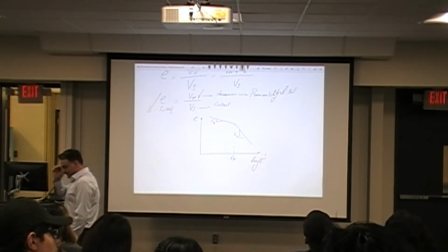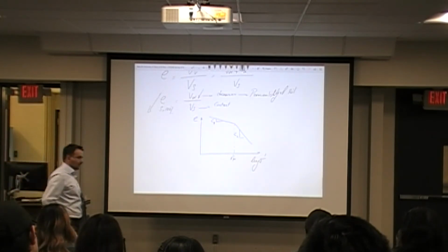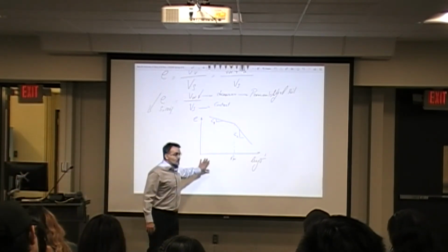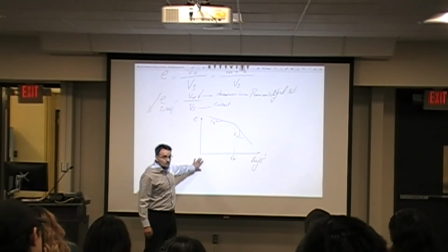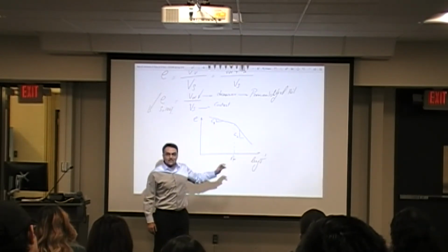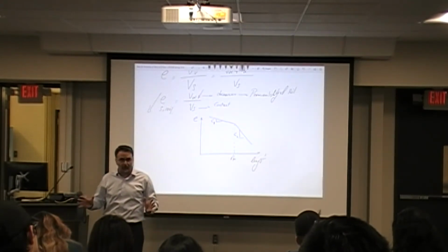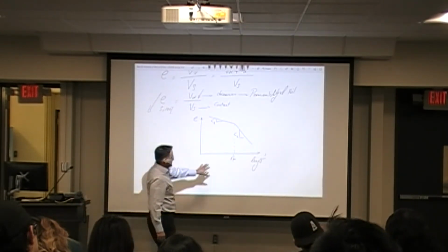All right, getting back to our discussion about the oedometer, or one-dimensional consolidation. Yes. All right, so let me just quickly recap what we want to get from this plot. We want to figure out the sigma prime p, and that would be the maximum past pressure that the soil has ever experienced in its lifetime. Right? So that would be one parameter that I'm interested in.